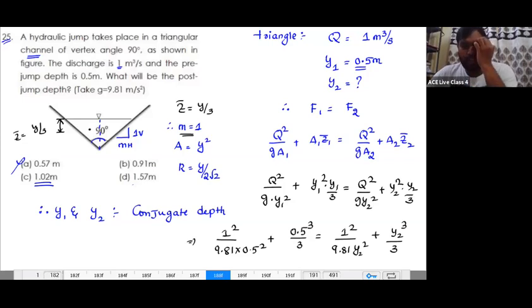But basically, what are the equations that have been used in the entire hydraulic jump? How many equations have been used? One, q squared by g equals y1 y2 into (y1 plus y2) by 2. Two, the sequent depth ratio y2 by y1 equals (-1 plus root of (1 plus 8 Fr1 squared)) by 2. That's it, and based upon those two only we have derived everything. And how did I get q squared by g equals y1 y2 (y1 plus y2) by 2? By equating the specific forces.